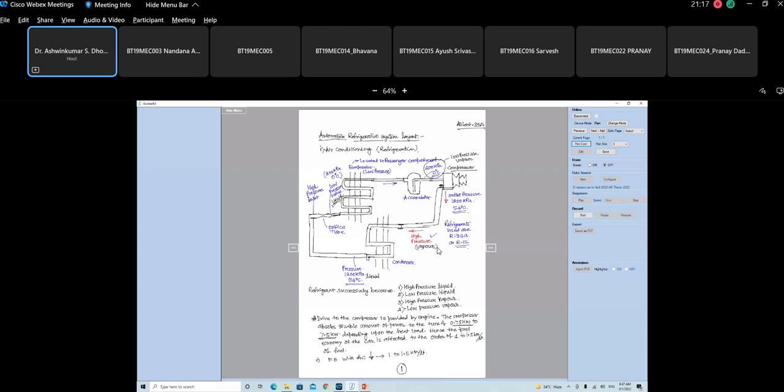So that is why, when they claim the fuel economy, people will ask you whether it is with AC or without AC. This is the estimate, basically, of why the fuel economy is getting affected: because the compressor requires power from the engine to run, or to recycle, or you can say to circulate the refrigerant.